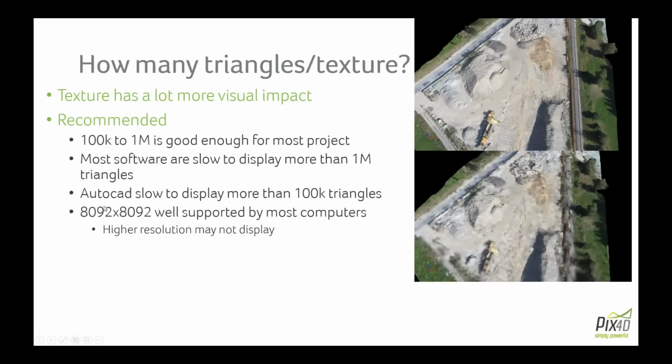Now, if it's just to visualize it in the ray cloud, in Pix4D Mapper's ray cloud, then we made some effort to make it quite nice to display a high number of triangles and texture. So 1 million and the texture at 8,000 by 8,000 should work perfectly fine.